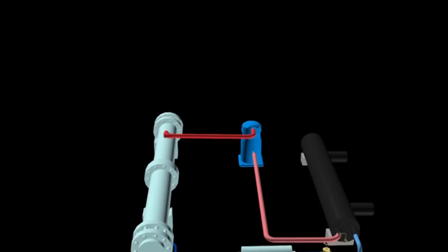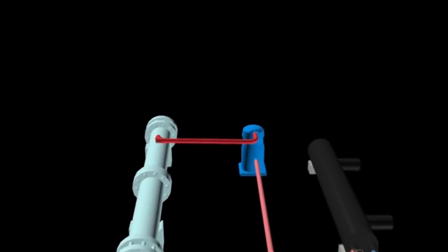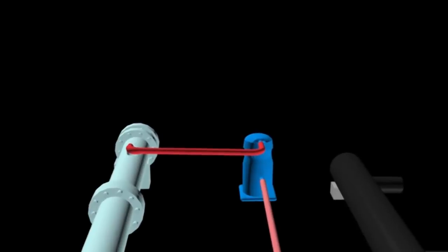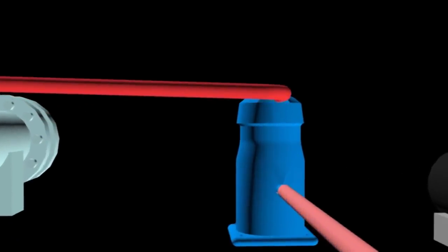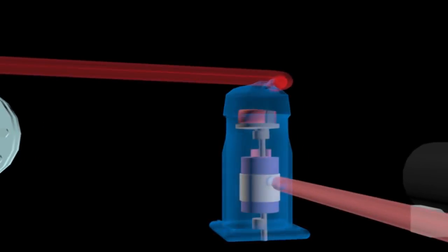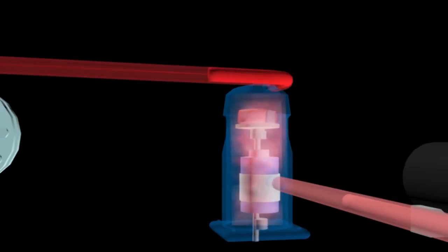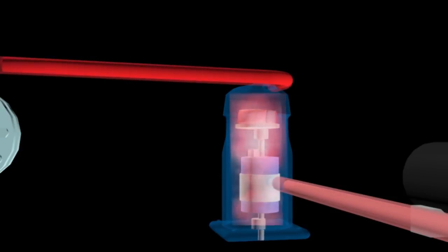Compressor. Compressor works to increase the pressure of the refrigerant. In addition, it also serves to increase the temperature of the refrigerant higher than the temperature of condenser water so that the heat transfer can occur in the condenser. The refrigerant enters the compressor as low pressure gas and exits as high pressure gas.